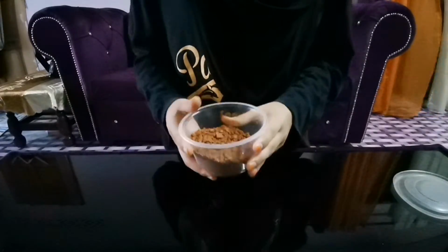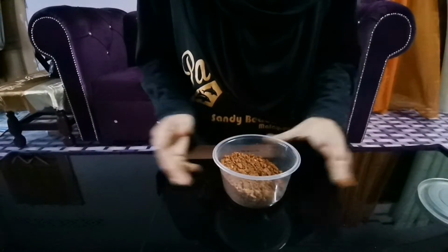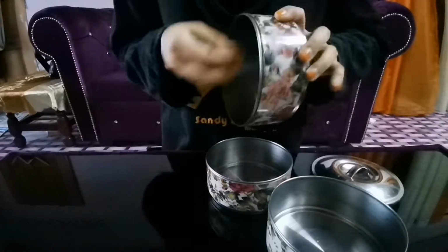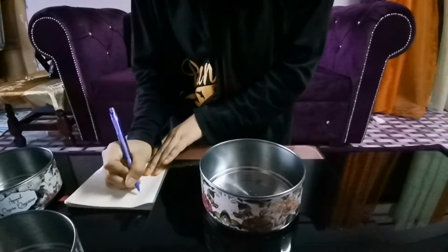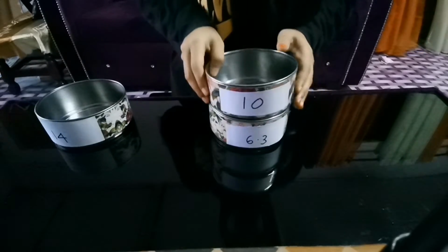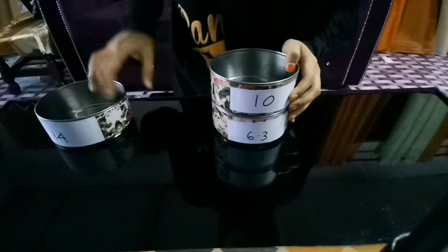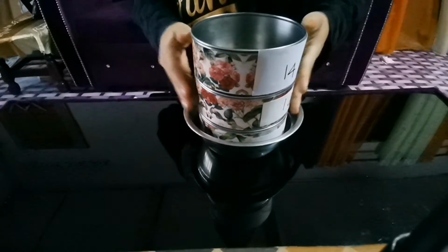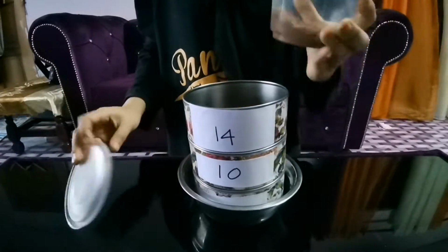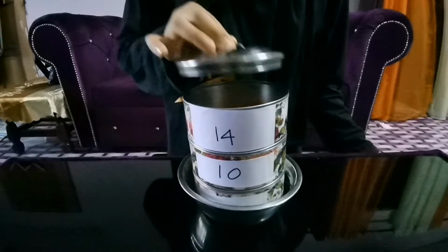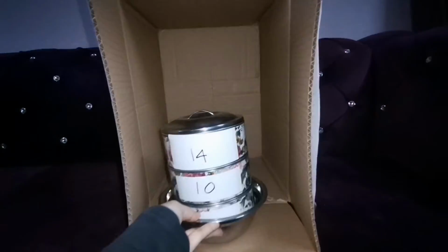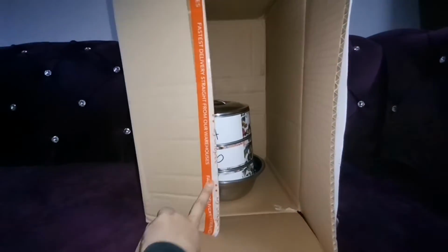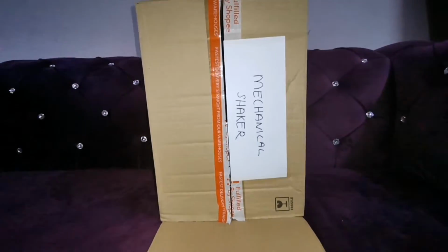Prepare the soil sample and record the weight of the dry soil sample. Clean each of the sieves to be used and record the weight. Arrange the sieves in order with the largest opening of sieve size at the top to the smallest at the bottom. Place the pan below the smallest sieve size. Carefully pour the soil sample into the top sieve and place the lid over it. Place the sieve stack in the box that acts as mechanical sieve shaker and shake for 15 minutes.